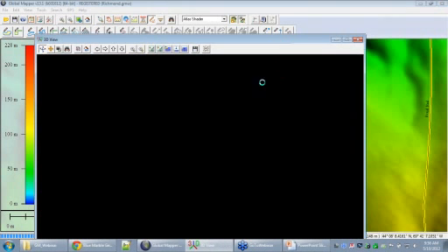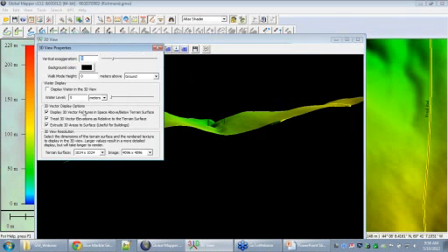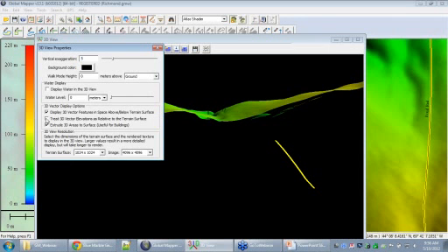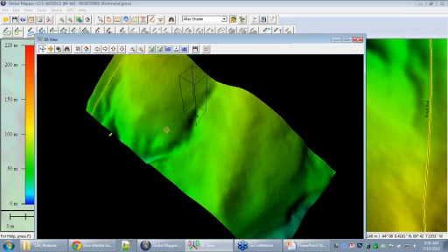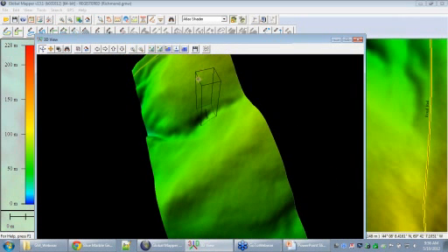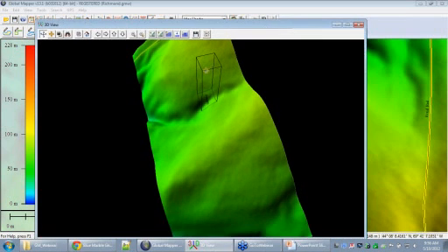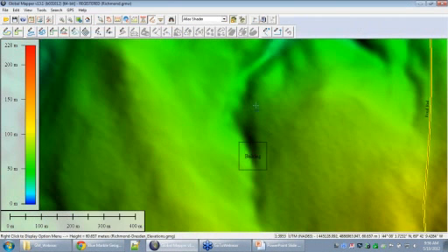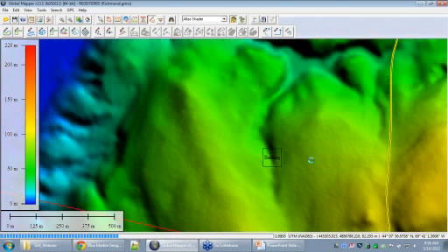We can go back into our 3D view. And once our 3D view renders, I'm now going to toggle that off. So now instead our 3D vectors' elevations are going to be relative to an absolute sea level height. And then you'll see the top of our building is actually squared off in there. So regardless of what the terrain is underneath it, the top of our building is going to be flattened off at that height.